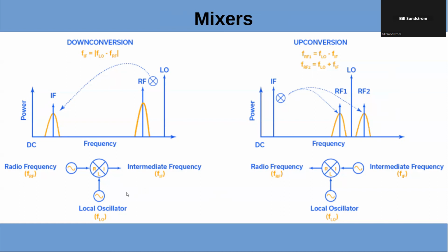So this is sort of a superheterodyne receiver and a transmitter. I was just trying to see if there was any relevant information on these, because it's not my slide. But it looks nice. You're taking your RF in, you have your local oscillator, and it takes it down to the intermediate frequency. The other side, you're taking your IF and going up in frequency.